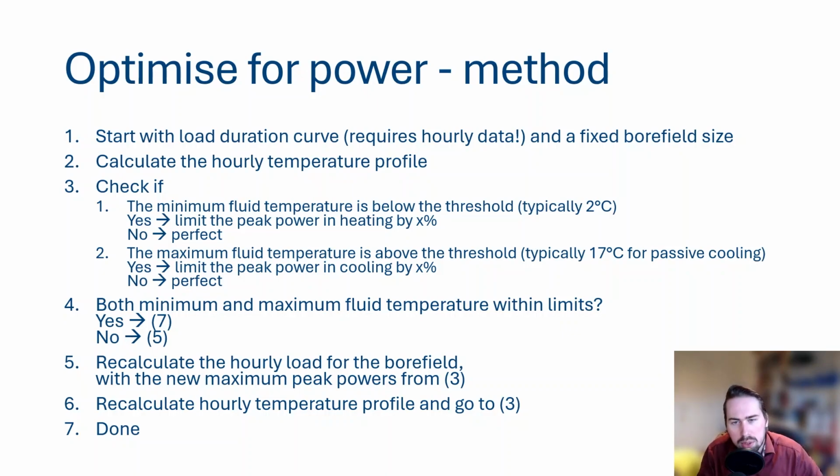But the most important thing for this methodology is that you start with hourly load data and a bore field of a particular size. And what you do then is you calculate the temperature profile with the hourly data, and you're going to check in step 3 if the temperature limits are crossed, basically.